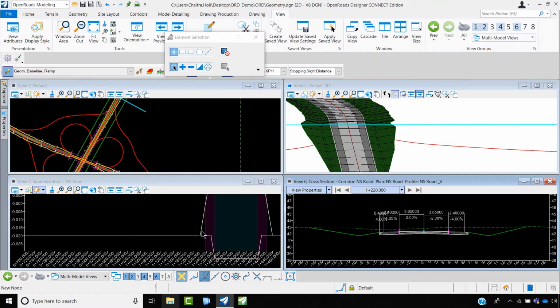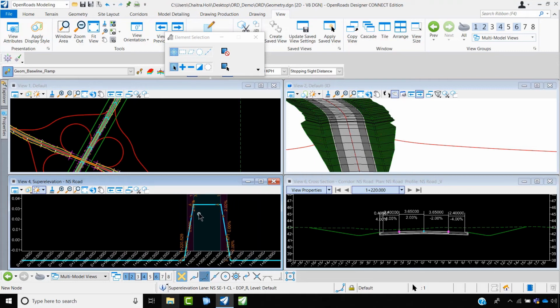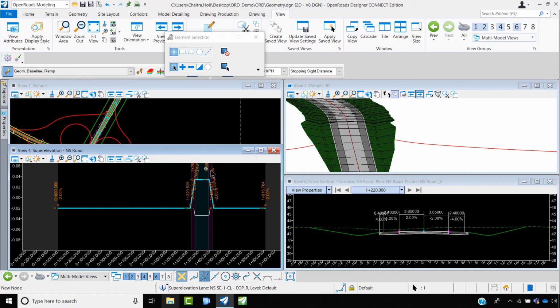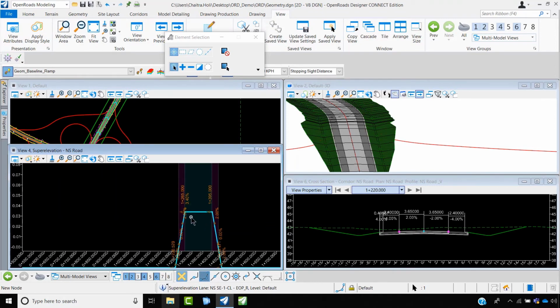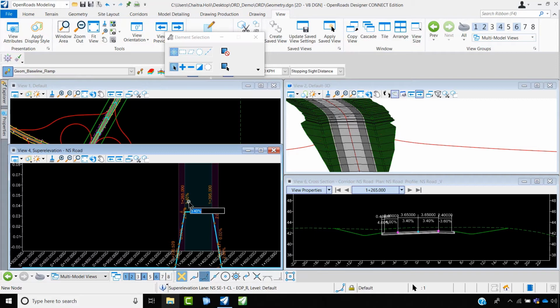over here, where it is ahead. It is 265, where it is showing me the super elevation of 3.4%. Instead of 3.4%, say I give a super elevation value of 4% and enter over here. The moment I make changes over here, that got updated over here.